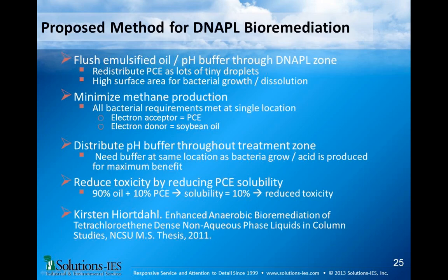But I've only dissolved a little bit more than 5 millimolar. There's really almost no improvement in removal. At this point, bioremediation isn't really doing any good. I mean, it's limiting downgradient migration, but it's not increasing the cleanup, because this stuff just doesn't dissolve fast enough. It has to dissolve before it can biodegrade. If it doesn't dissolve, you can't do any good.